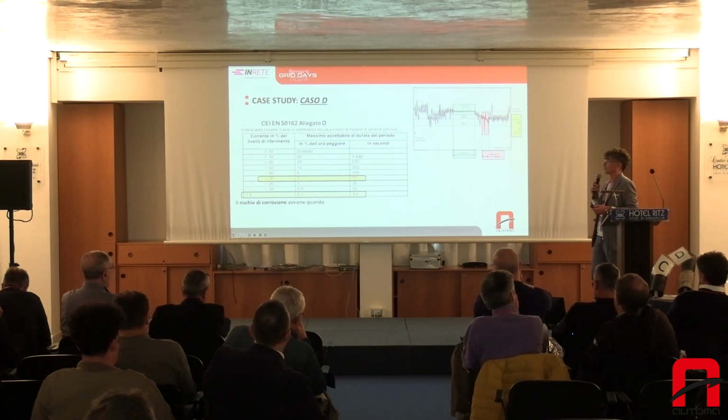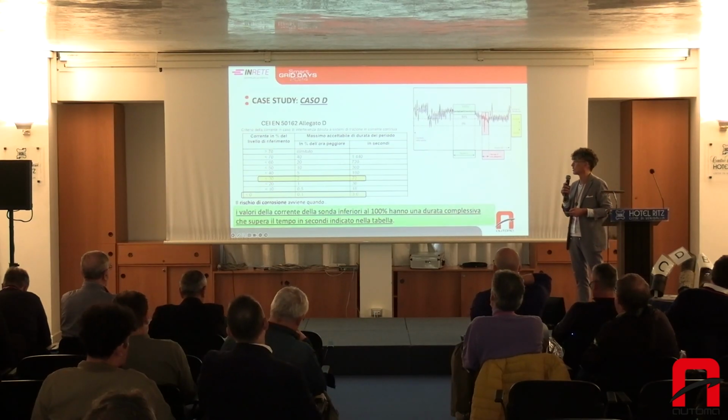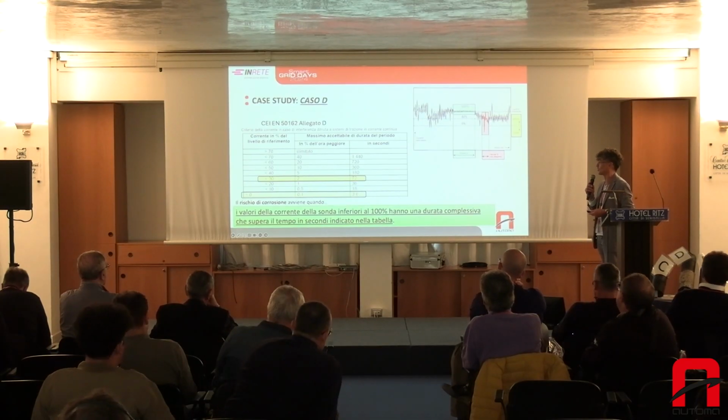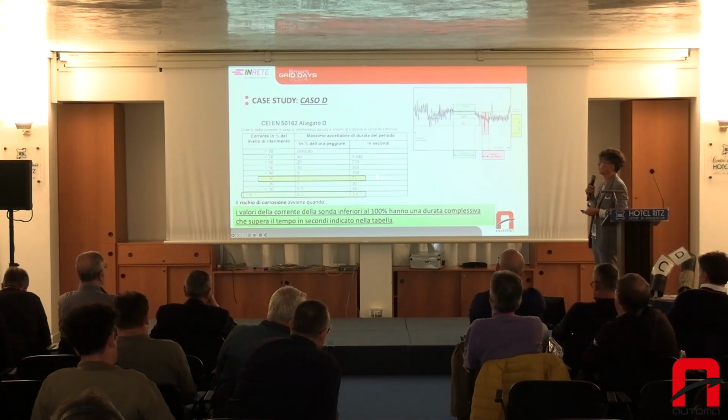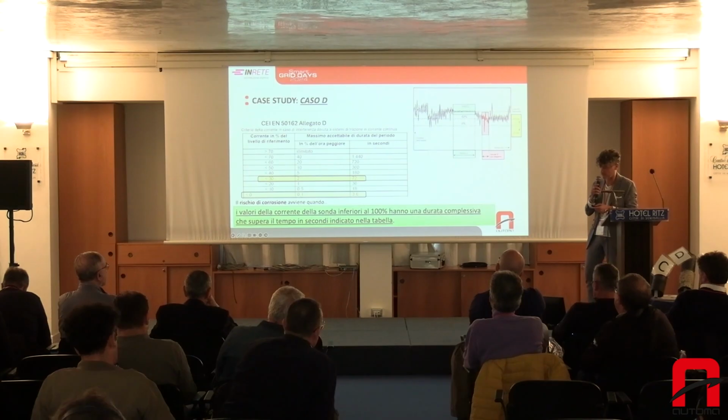Okay? Corrosion risk occurs when the values of the probe current are lower than 100% and last longer than the time indicated in the table.